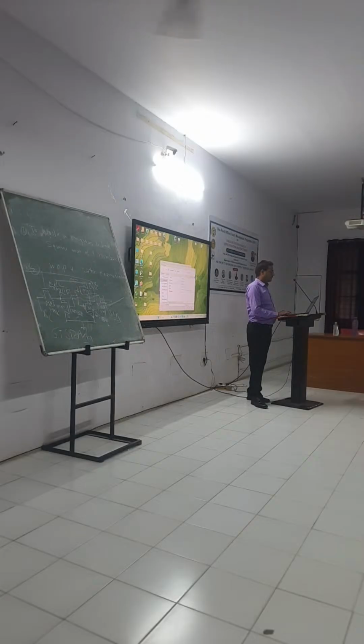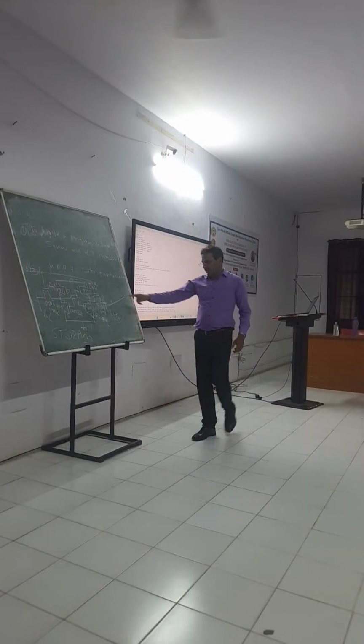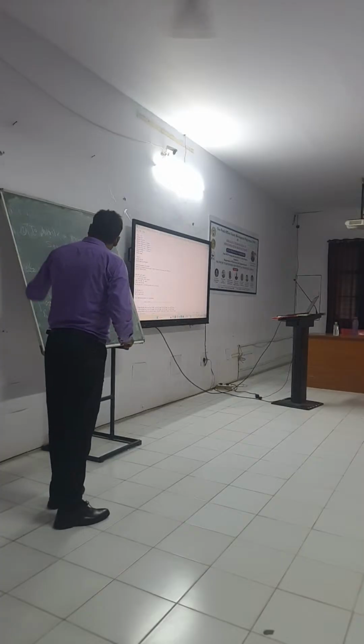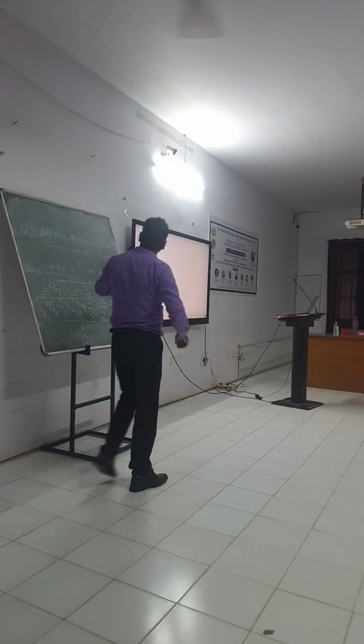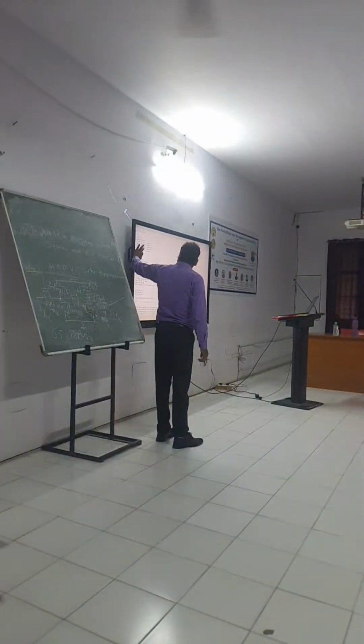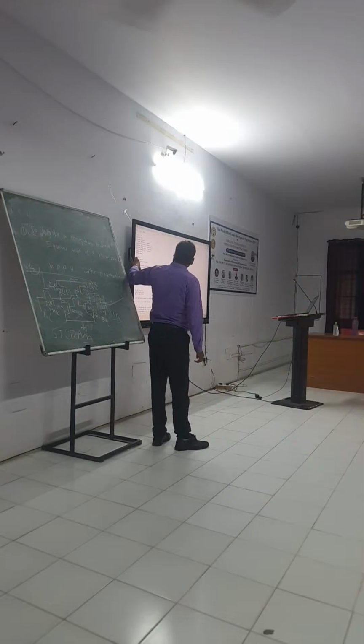Here I have written the code, I am just showing. This is the 6T SRAM, so here you can check its code. The same way, this is the code for this circuit. How will the system understand this circuit? You have to write the terminal names and device names, as you can check. The temperature of 27 means we are going to simulate at 27 degrees.